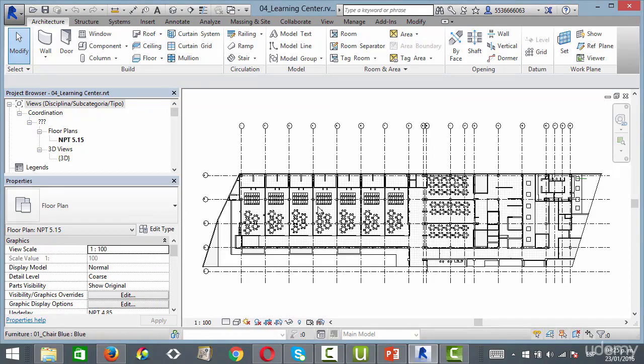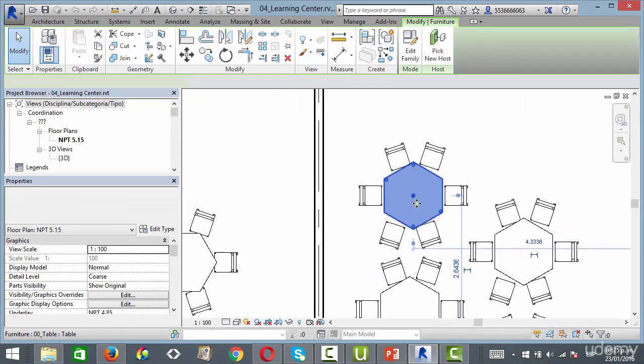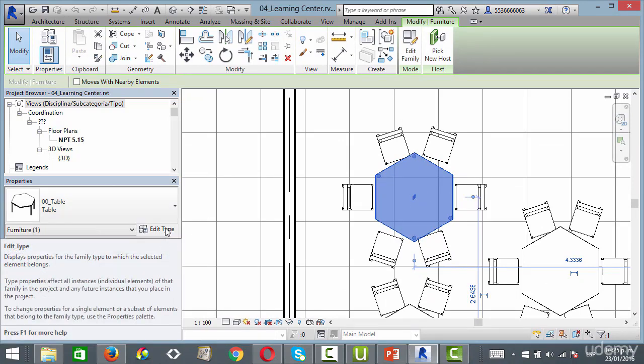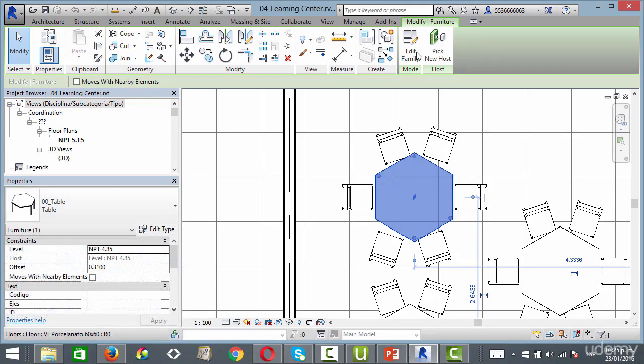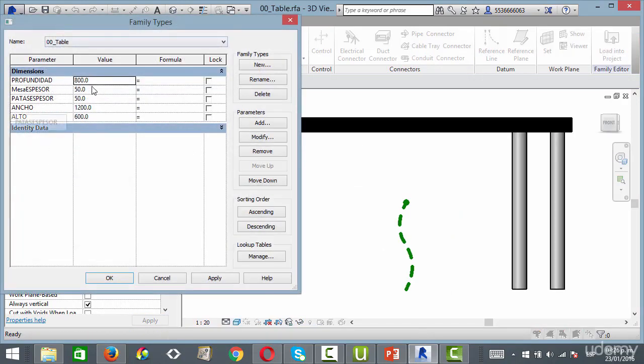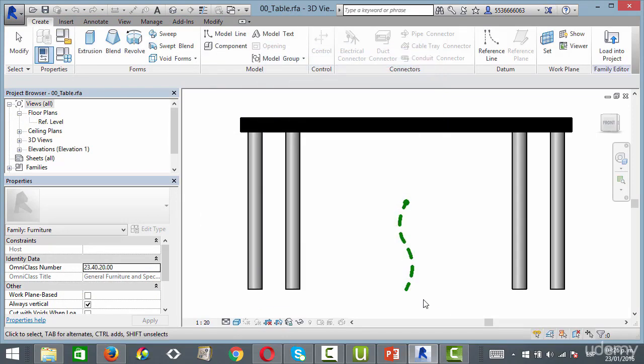Another really simple option that you need to know, that probably you haven't used, is something called the room calculation point, that is on almost all families from furniture, mechanical equipment, specialty equipment. And what happens is that you need to enable that they have a room calculation point. You can set it up from here, setting up the room calculation point, and this is how it looks.